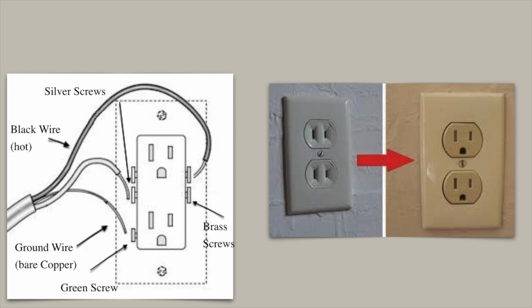The one essential thing a home inspector must inspect for is if an older home, pre-1950s, has modern 3-prong plugs. The inspector needs to make sure that the newer 3-prong outlet has been upgraded with a ground wire. Sometimes, when modernizing older homes, contractors will replace the older 2-prong outlet without running a new 3-conductor line to the outlet.